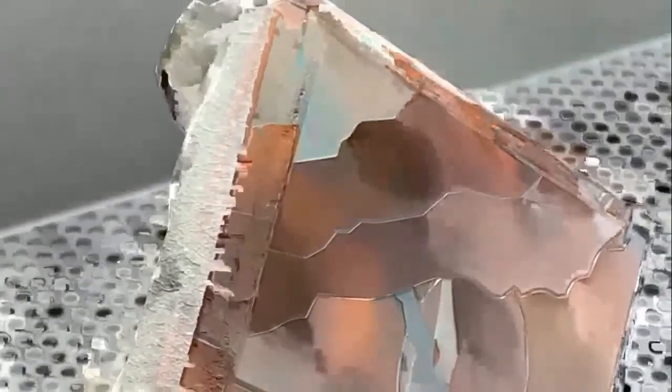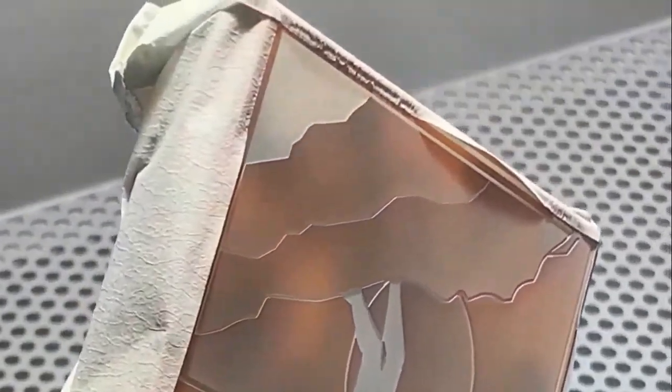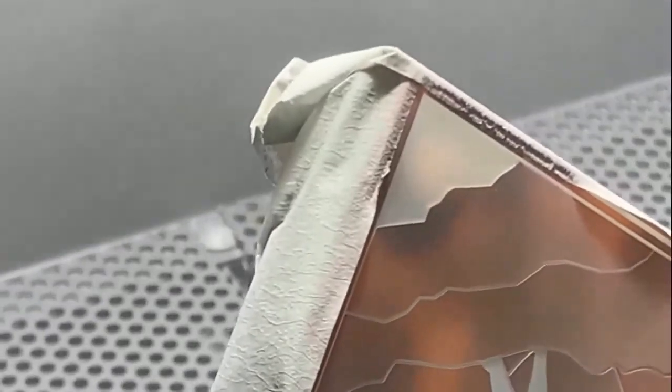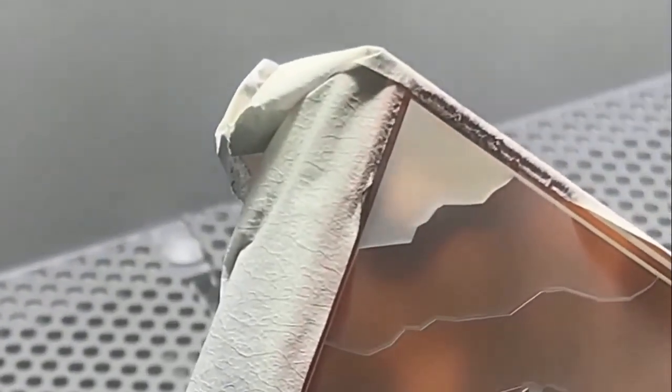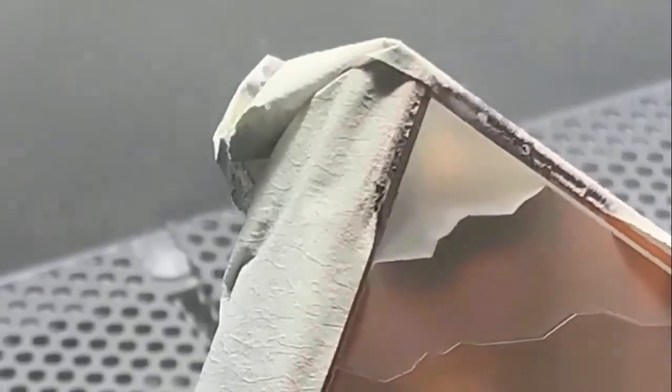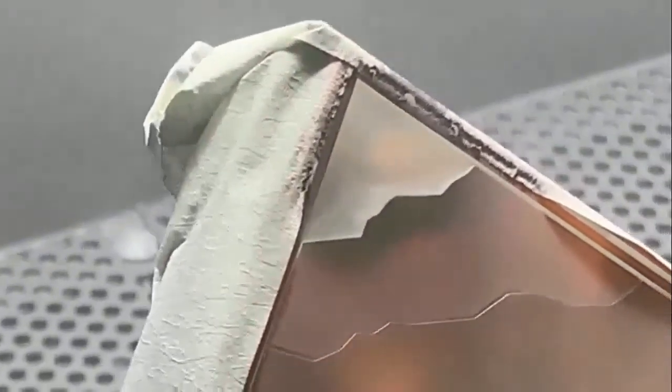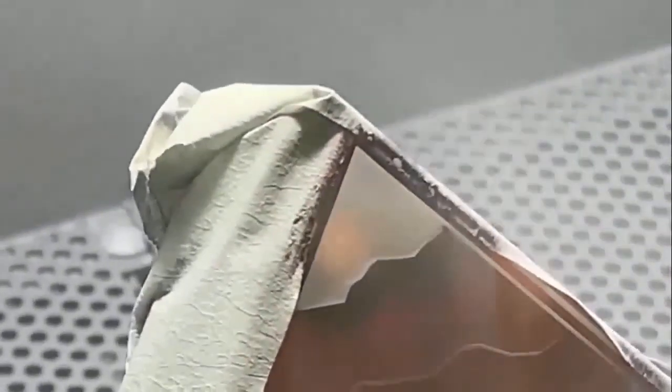So what we're doing here is we're creating multi-dimensions in the glass. Instead of doing 2 levels of sand carving, like before with the shade and a white, now we're going to do 5 different levels. So there's going to be 5 etching depths. And here you're going to notice the silicon carbide is eating away at the glass material, very smooth.